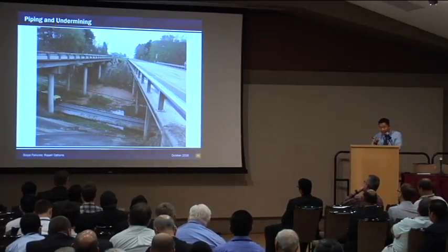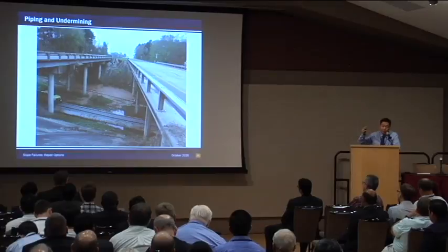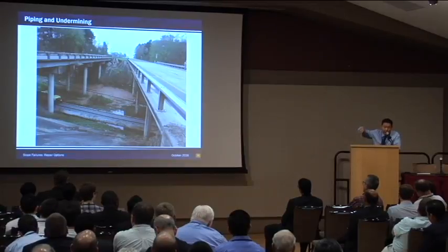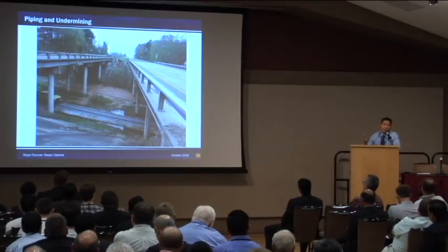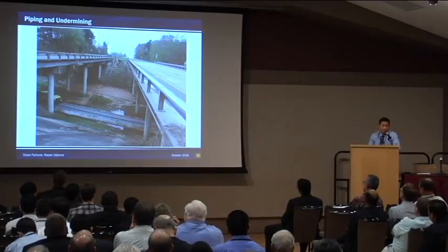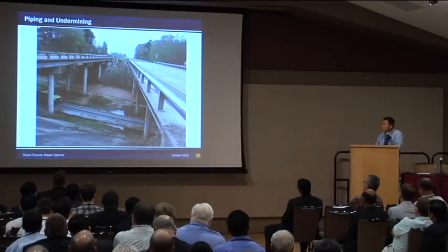So if you see the lateral stability is the issue, and if you have enough excess capacity, then you can consider the repair options that Christine presented in a couple of presentations ahead, like driving sheet piling at the back side of your bridge wall, and separating the lateral load pressure subjected to the wall. That is one of the possible options. And also, as Christine presented, put the retaining wall in front and make the back slope flatter. That's a very good repair option as well.